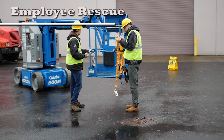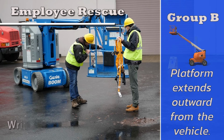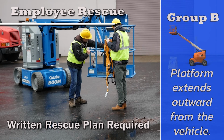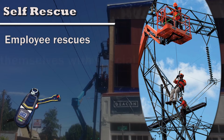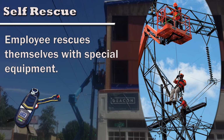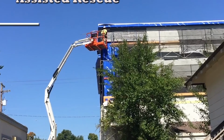Fall protection is required on all Group B work platforms. The employer must have a plan, in writing, that explains the methods for rescuing a person who has fallen from the platform. There are three main options for rescue. Self-rescue utilizes special equipment that allows the employee to rescue themselves.